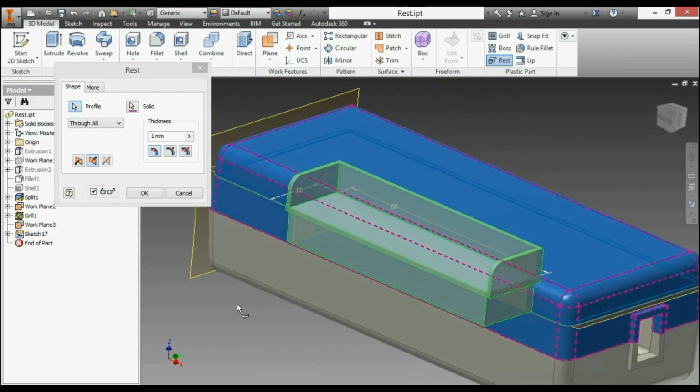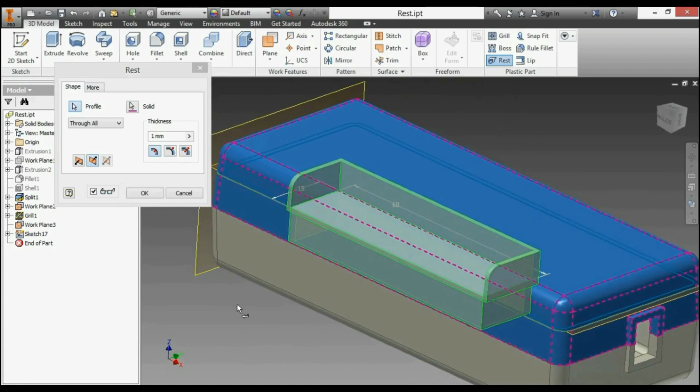As you can see, this is a way to create geometry that's recessed into your part to create kind of a shelf. Now this can also create geometry that goes out and above, so it can actually generate additional geometry, not just subtract geometry. And it really depends on the curvature of your plastic part, the shape of your sketch, and the location of its plane.